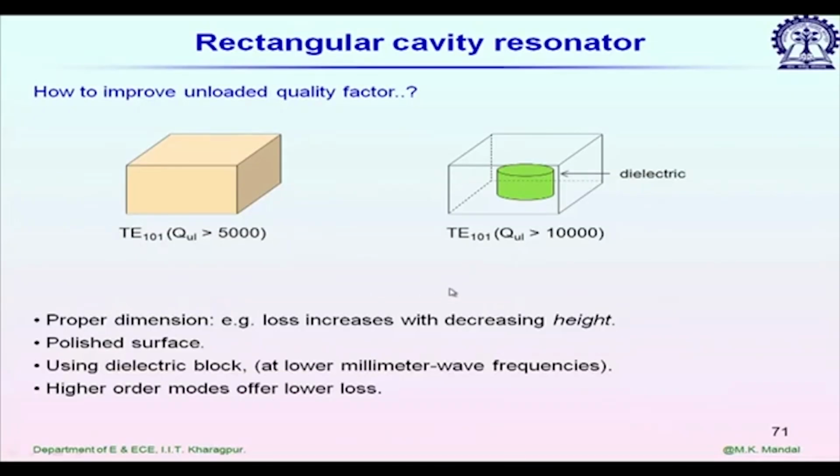So, air is almost considered free space or a lossless dielectric, but if there is water vapor present in the air, it becomes lossy, because water vapor absorbs electromagnetic waves. So, if you are using air inside, it should be dry, or sometimes people use an inert gas, and you have to make sure there is no water vapor present inside the cavity, otherwise it will become lossy.